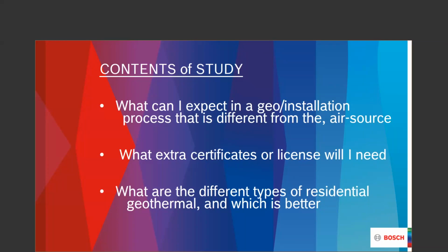That is one of the greatest attributes, besides the longevity of the equipment: instead of hoping that July's temperature is going to be a certain degree, I can look at my geothermal design and say July 2nd, that energy plant is going to be below this temperature. If it's below this temperature, I'm going to get this output. And with that output, if my kilowatt rate is 10 cents a kilowatt, my electric bill is going to be that. I can't do that with an air source system, but I can do that with a geothermal system. So which type is better? Again, it's all about economics.